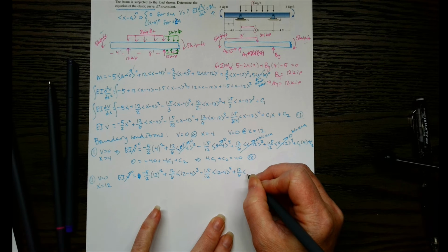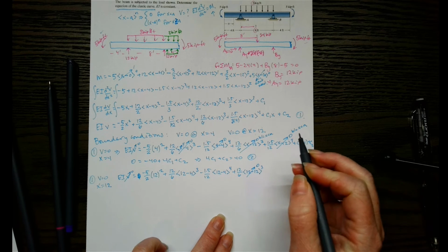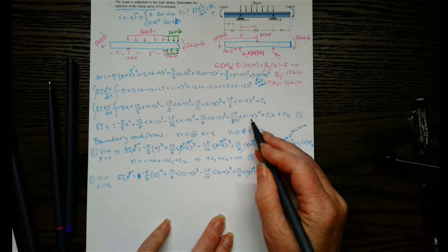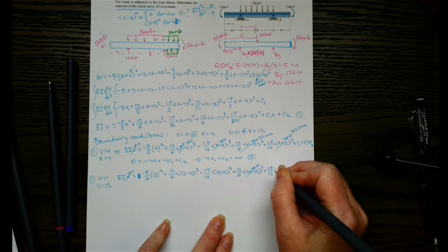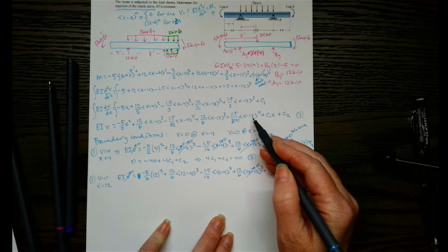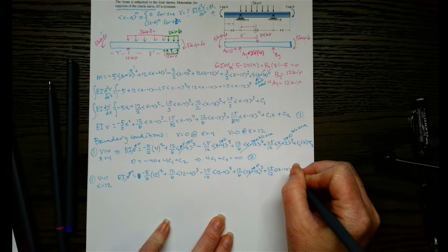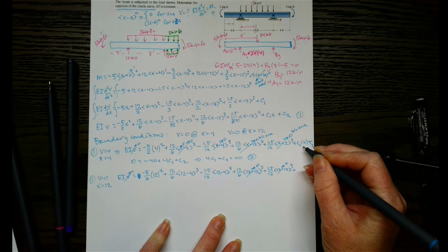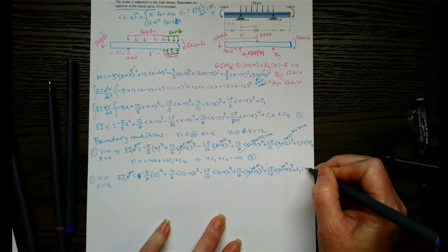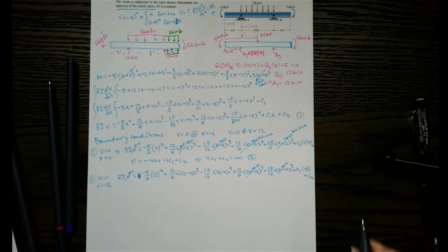X is equal to a in this case, so we're going to do 12 minus 12, power 3, but that obviously goes to 0. We're going to get the same thing with this one. All right, so 1.5 over 12. X is the same as a, because a is 12, x is 12. So just do 12 minus 12, which gives us 0. And then we're going to have plus C1 times 12, because we're plugging in x, and then plus C2.